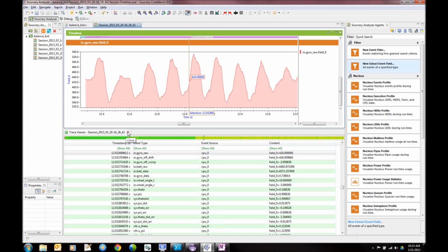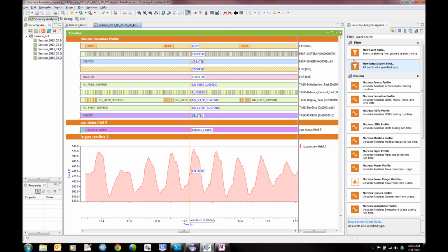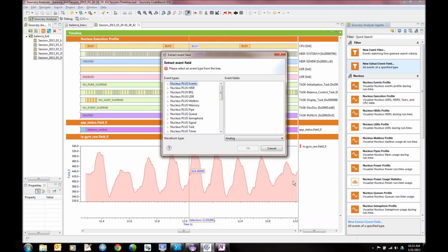And now I'm going to add, so we get the raw gyro count and then we do a bunch of signal processing on it, right? So there is a filter that captures the offset drift. So we basically subtract the gyro offset from the raw value, and then we scale the raw value to provide us angular rate of fall in degrees per second. So that's all the conversions that happen. So I'm logging the gyro input data path at all of those stages.